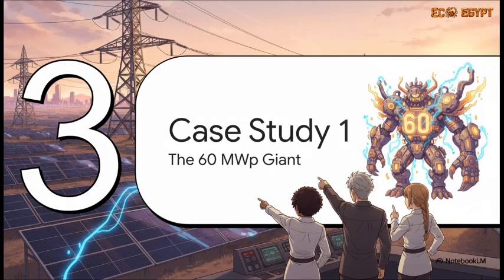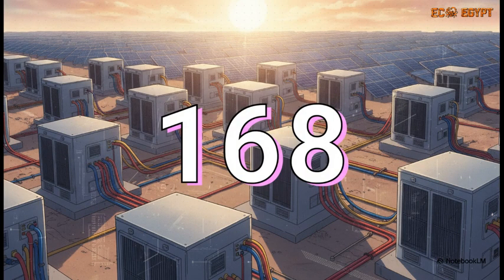All right, Section 3 brings us to our first real-world boss fight. Case Study 1, the 60-megawatt peak giant. 168. I want that number to just sink in for a second. That is the quantity of massive 330 kVA string inverters required for this grid-connected plant. Coordinating the DC inputs and AC outputs for 168 of these units requires an entirely different caliber of engineering.